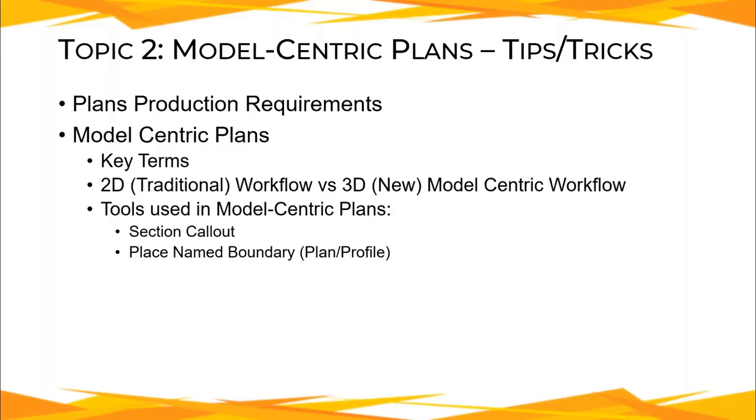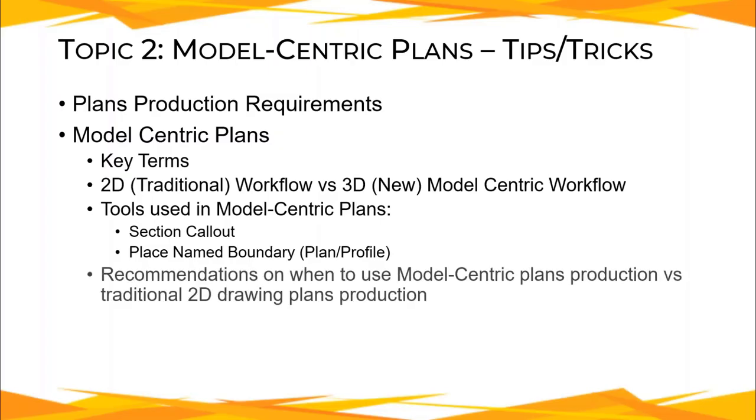Section callout is probably one of the main ones that Heather showed earlier. We do use that in a lot of different applications. Probably the second most used one is the name boundary tool, so we'll cover that one here too. We'll give some general recommendations on when to use model-centric plans production versus just traditional 2D drawing plans production. And we'll get some bonus tips and tricks in here with some display styles and some display rules, some things that some people might not be familiar with.